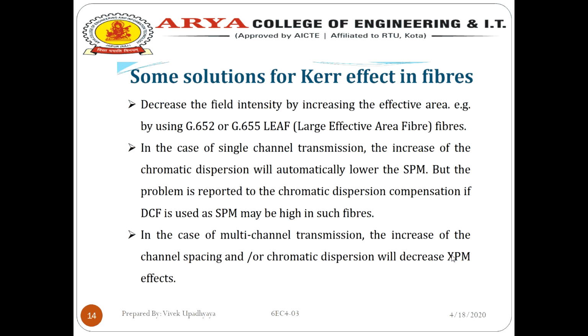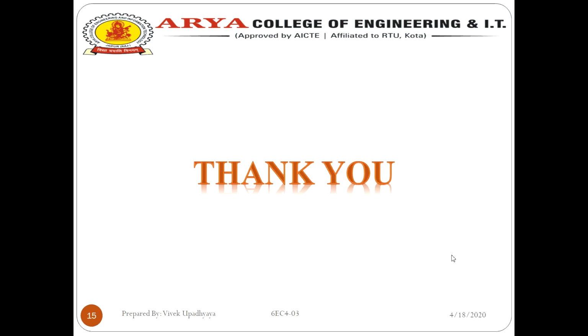Another solution in this case is multi-channel transmission. The increase of the channel spacing and the chromatic dispersion will decrease the cross phase modulation effects.